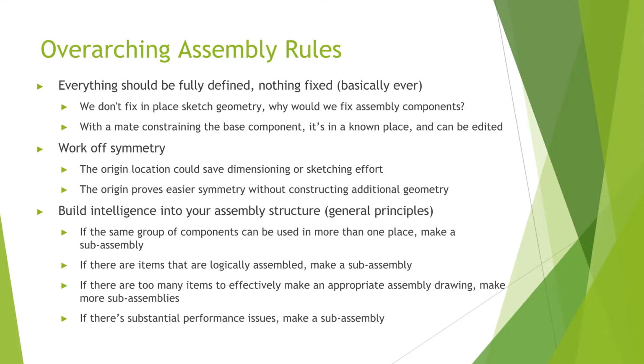So I'm going to put these 10 things together all the time consistently on the bench, and then I'm going to put it in the machine or something. Sub plates and that kind of thing. If there are too many items, if you're trying to make a detail print and you realize you're sectioning it 3 times and doing 10 balloons and then doing a detail view and a break view and a whole bunch of stuff just to try to communicate what it is on the print, you probably have too many parts in your subassembly. Possibly make more.